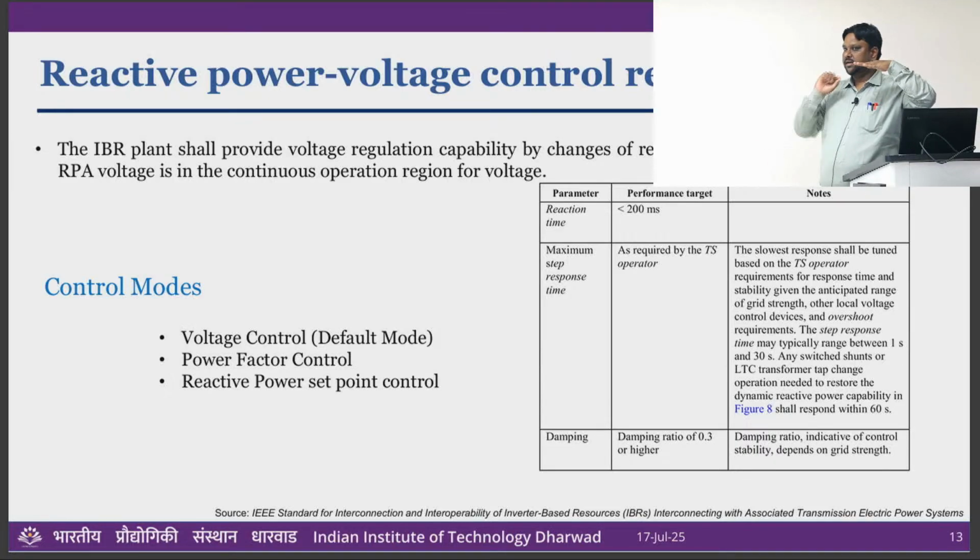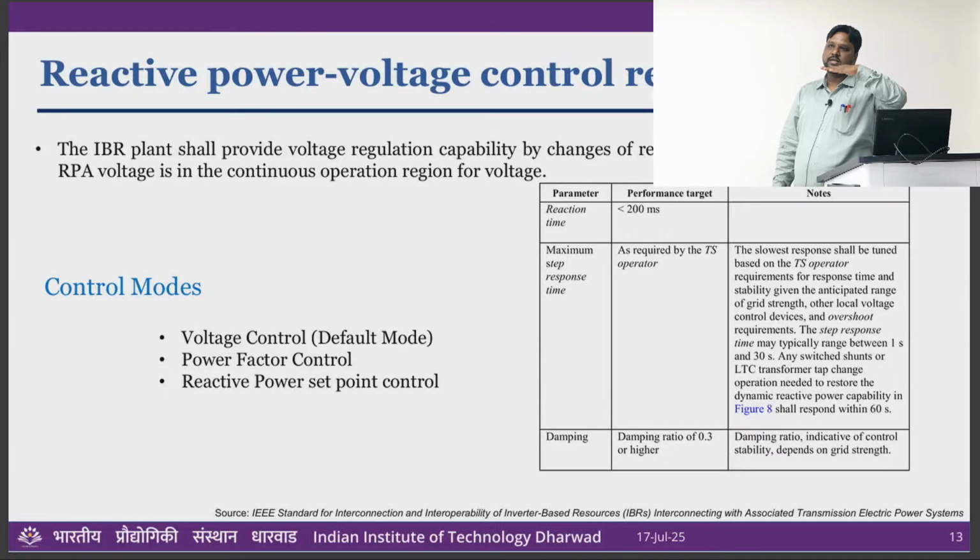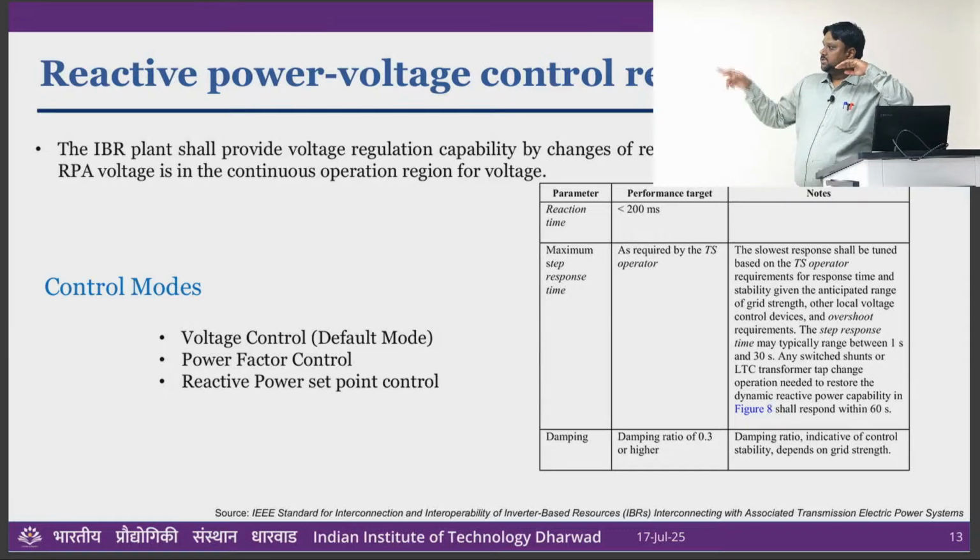They will give you a signal to the IBR unit. Okay, this is your set reactive power now. You have to follow that. Okay. So all these controllers, again I am saying, are not at the single IBR unit. It is a plant level controller.